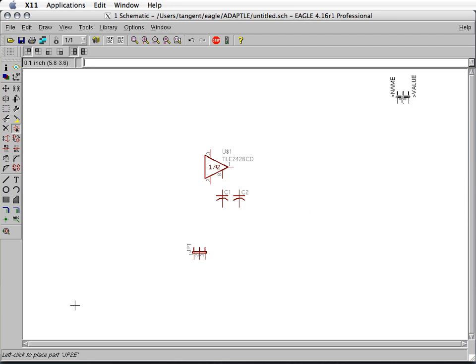I could put it up here and the schematic will still work, but it won't be obvious why it's way over here and up and to the right. So that's just a kind of a logical place to put it. So you want your schematics to flow in some logical fashion, because schematics are first and foremost for the human. Create them so that they're readable first, and then so that they work for the tool second.